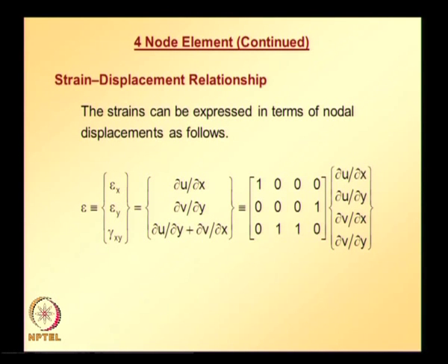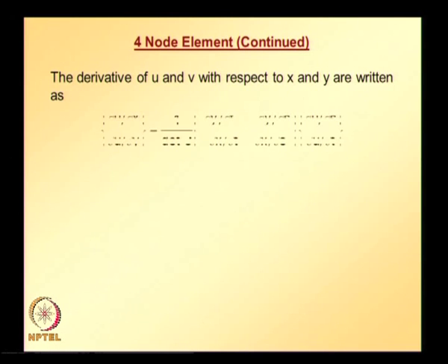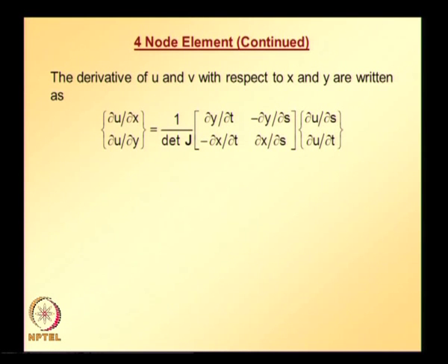You are familiar with this definition of strain. Now, this vector consisting of partial derivatives of displacements can be rearranged as shown in the later part of the equation, and the partial derivatives of displacements with respect to x and y can easily be calculated using this relation.